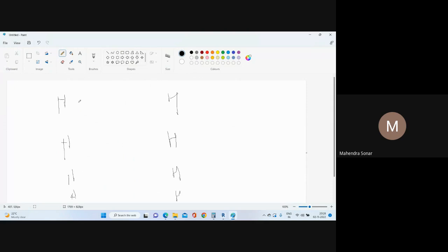And then after that you need to provide some wind columns here also as per design, like that. So you need to set this distance, the center to center distance. Okay, so suppose I have calculated the total distance, just consider this is 3 meter, this is 3 meter, and this is also 3 meter.